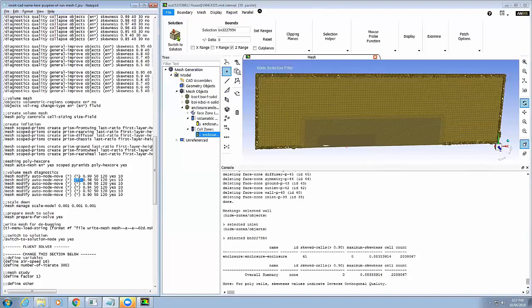The difficulty is that if you don't understand that, you can stand here for the next day trying to change the mesh settings to figure out why it's better, not knowing that the truth is you're just making a really sharp angle in geometry that needs to be fixed. That's the hardest thing. I know when things go wrong from experience. Unfortunately, I can't teach that to you, which is one of the reasons I always say if something goes wrong and you persist a couple of times and it's screwing up, just come to us. Maybe we'll be able to tell you what it is earlier. Does it make sense? Yeah, no, I got you. All right, so that's done.